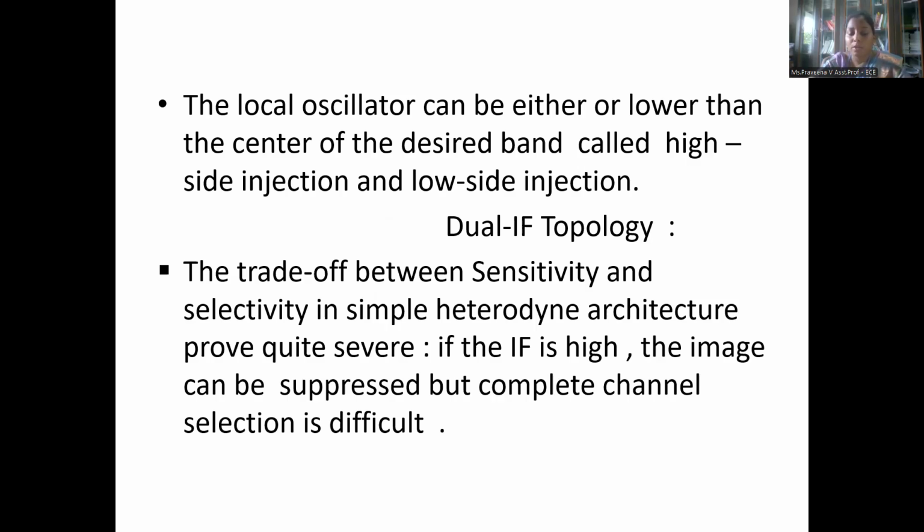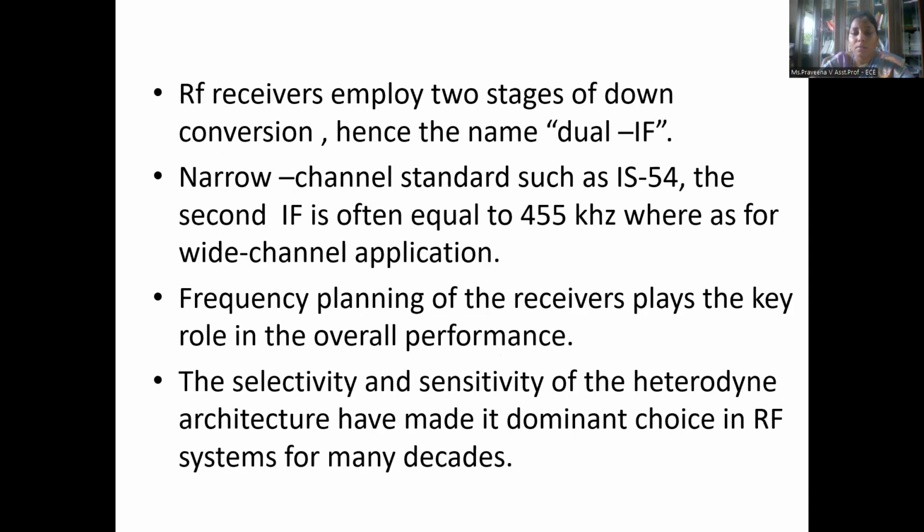So we are going for a dual IF. Dual IF architecture balances this by using the first IF for image suppression and the lower second IF for better channel selectivity. So there will be two stages in the dual IF topology.